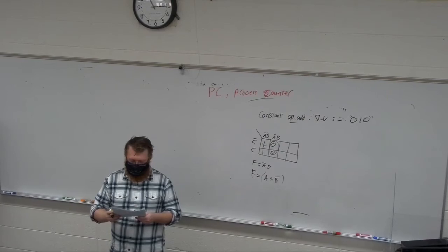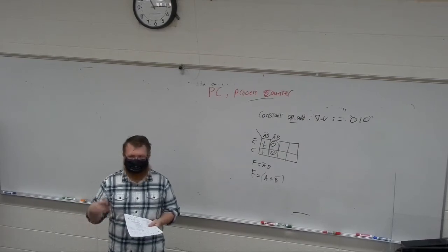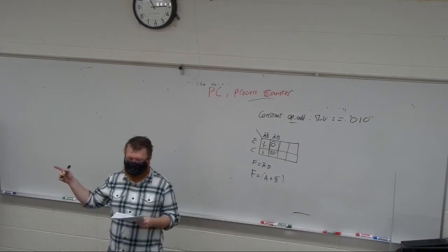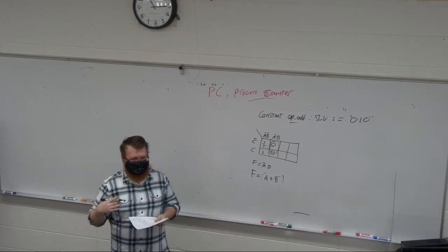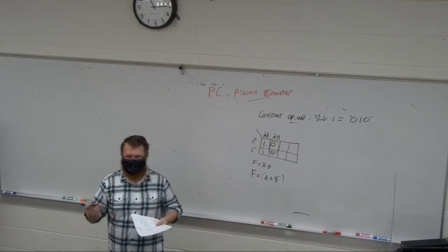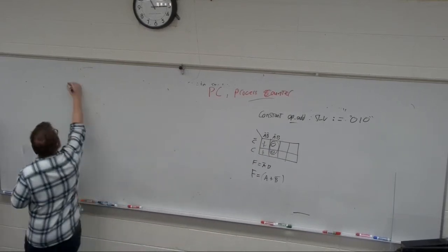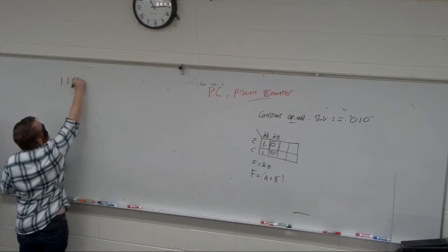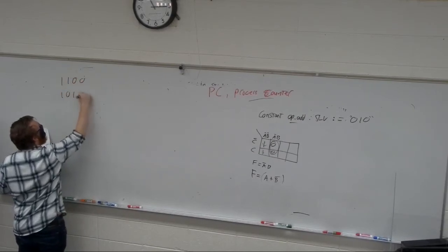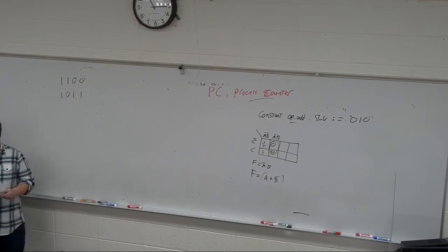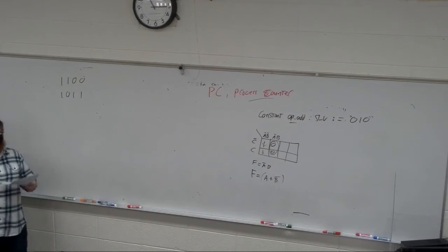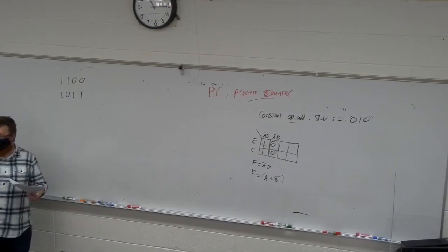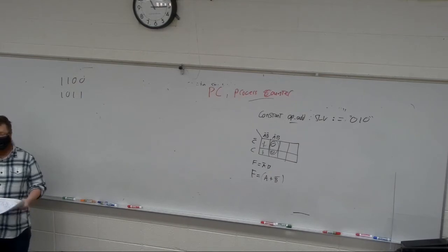So the way I did it is, instead of taking the A less than B, A greater than B as the output, I just created something called the propagate, right? So the idea is, if I have two 4-bit numbers, I want to start with the greatest bit, the most significant bit. Because if the most significant bit is larger in one number than the other, it doesn't matter what the rest of the bits are doing, right?